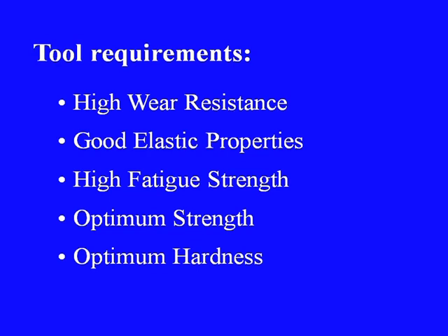Then it should have optimum strength because this will have to withstand the impacts of the abrasive particles as well, and abrasive particles are usually very high strength, hard materials like silicon carbide or boron carbide etc., and then it should also have optimum hardness.